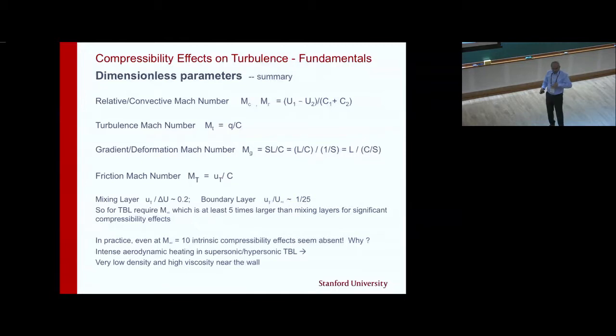So a shear layer or mixing layer has a momentum flux going from the high speed stream to the low speed stream. So that Reynolds shear stress could be used, or that's the shear stress. Assuming some density, one could derive a U tau based on that. It's not traditionally done, but it should be done. For a boundary layer, of course, this is very common.